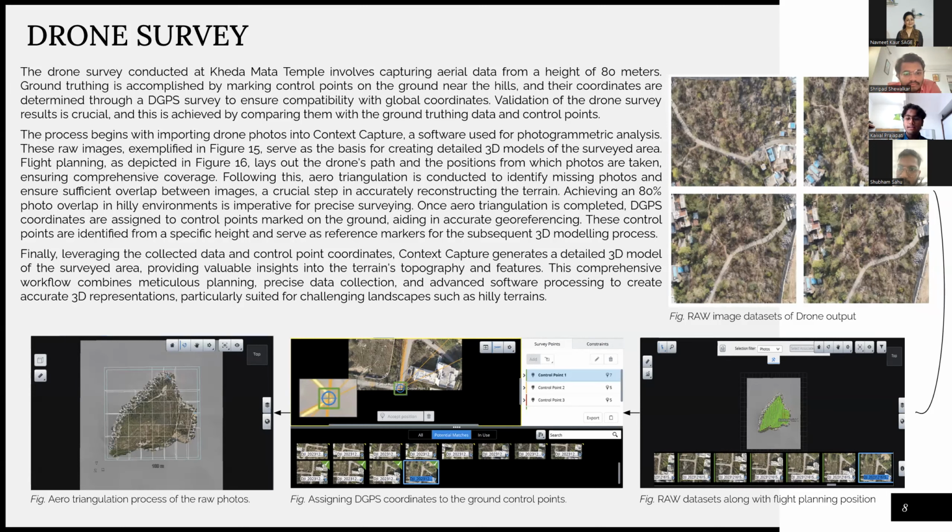We take 3 photos of a single point, which will have X, Y, and Z data of the ground. These are inputted into the actual images that the drone has taken, and it will autocorrect its location in all 3 axes to form a correct output.